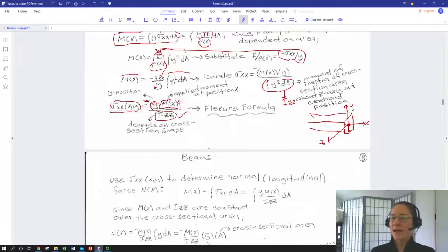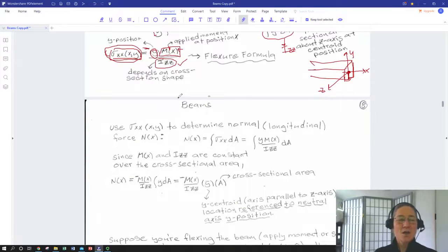The internal moment at that point is in many cases going to be a function of your loading, but if you maybe have an existing design and you are re-rating it, how big of a truck can I drive over this? How much can we put on this? How much weight can it carry? You would use the other factors and put a safety factor on your sigma xx and say, yea, verily, this can only be so big. So this is known as the flexure formula, because it is looking at stresses that are due exclusively to flexion.